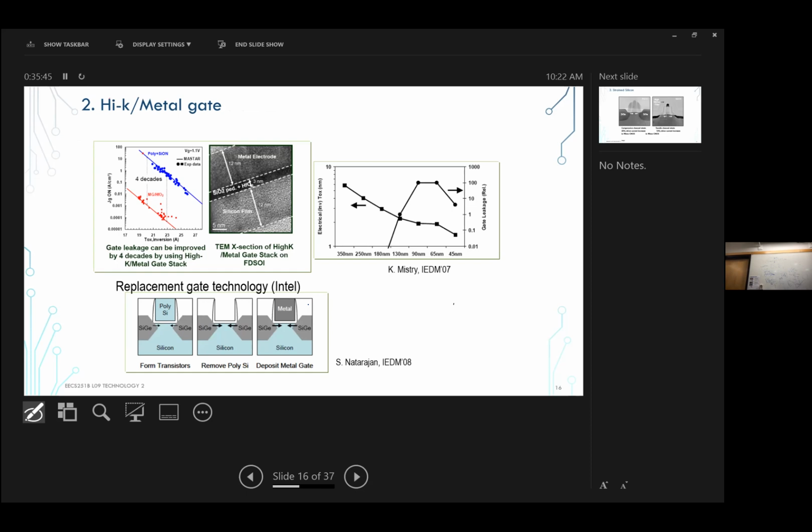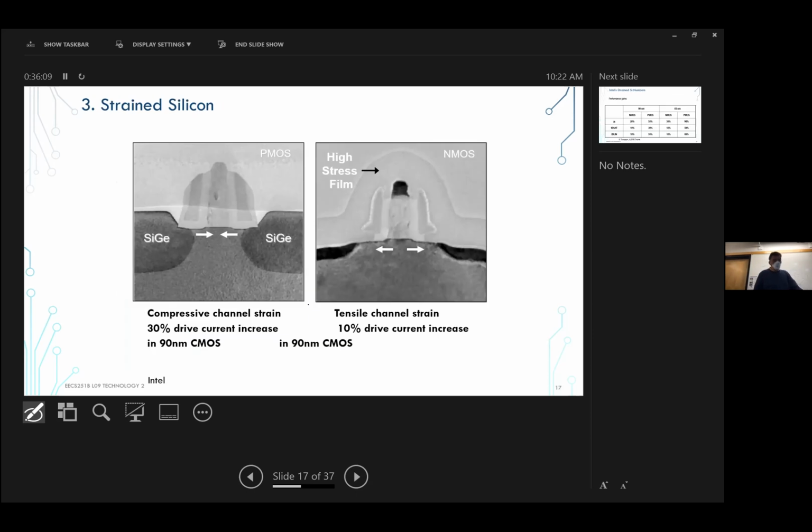The native silicon dioxide that we had in similar devices has been replaced with high-K metal gate, and since then the leakage is pretty much gone. So we don't have to worry about that. What's the implication for design? Early on, when there used to be a replacement gate around 45 nanometers, there were implications for design. Now, none. We just enjoy it. Technology people have solved that.